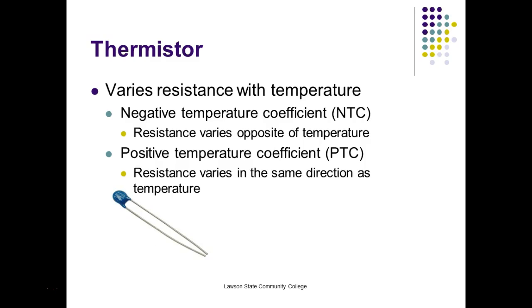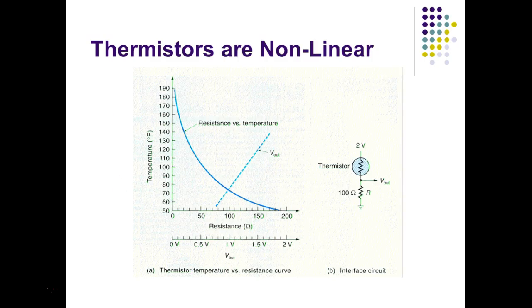So how am I going to take something that has a resistance that varies, and turn it into a voltage, which would turn it into a current? Well, Ohm's law has something to do with it, but what type of circuit would it be? It's a very complicated circuit. So I've got two options. I'm just going to put it in series with a resistor, right?